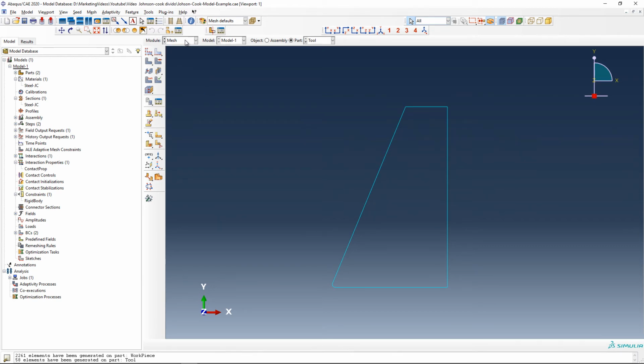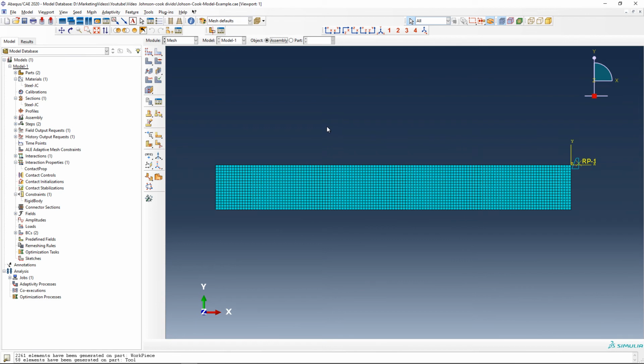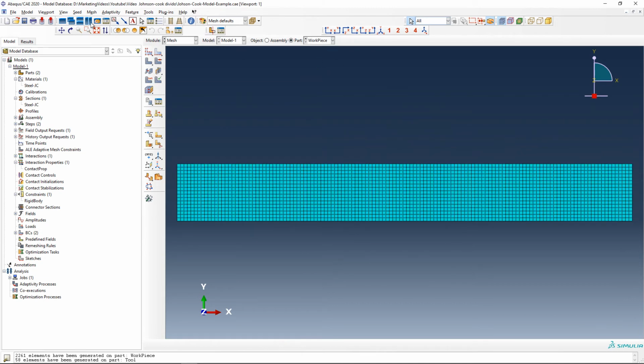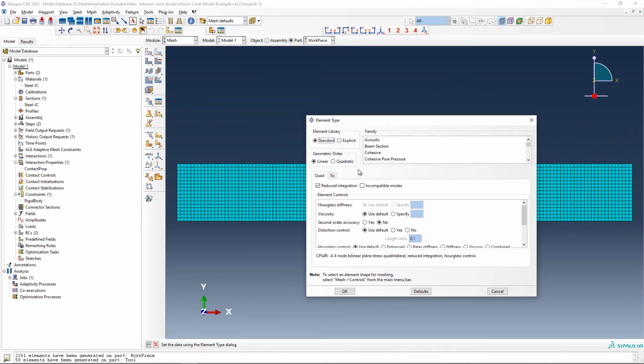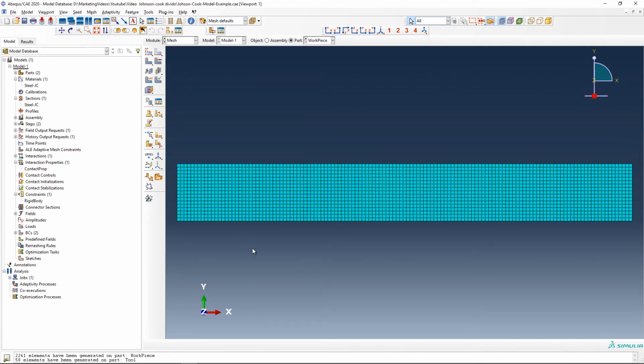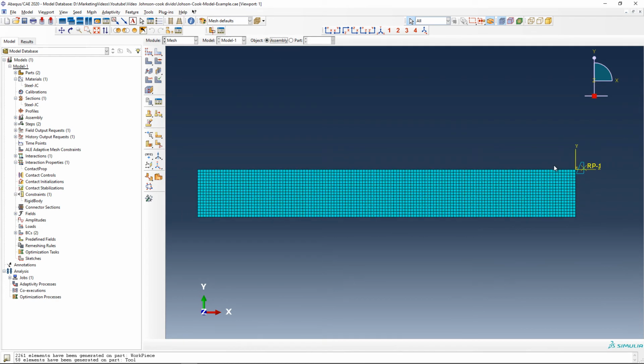Now, an important thing that I forgot. In the workpiece, you have to select explicit, sorry, to have element deletion in Abaqus. So I'm going to put explicit, and for element deletion, we're going to put yes. So I think I have chosen everything.